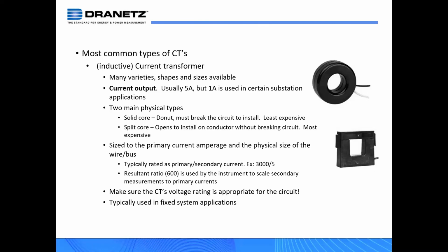So when you have your power readings, and a power reading says that you're negative on one leg, then it usually means one of two things. Either you have power flowing in the opposite direction, which might be the case if you're dealing with an alternative power source, or the most common, your current probe is reversed.